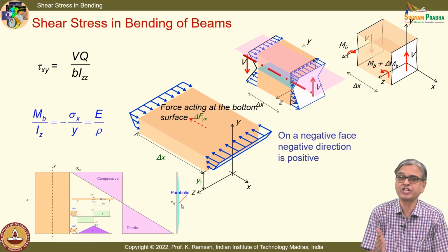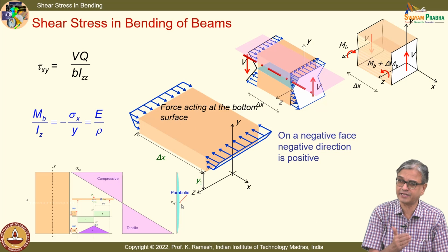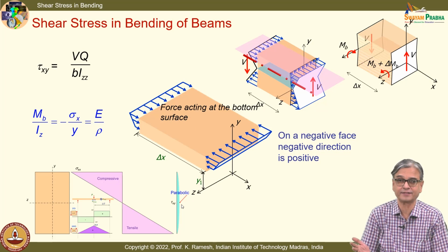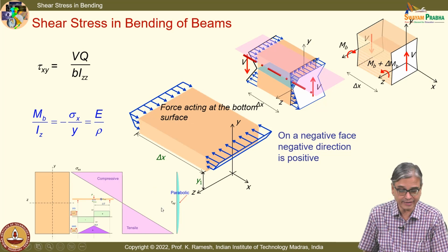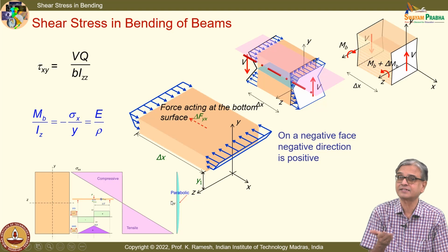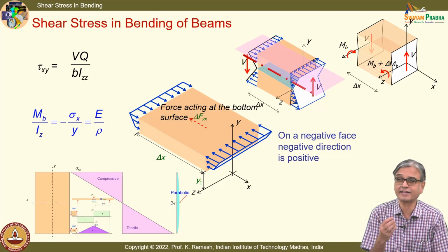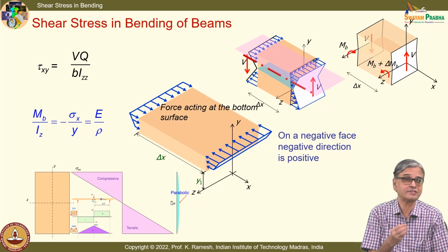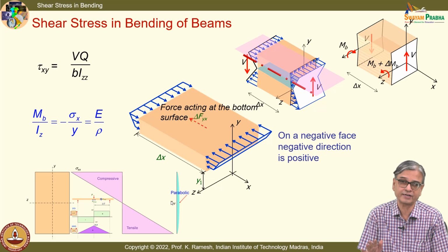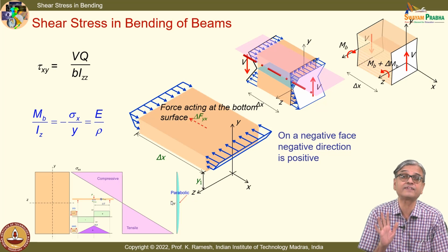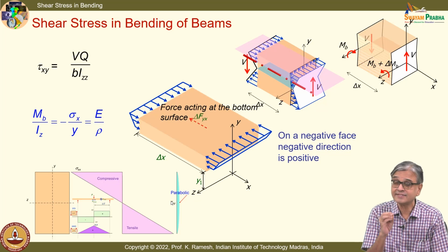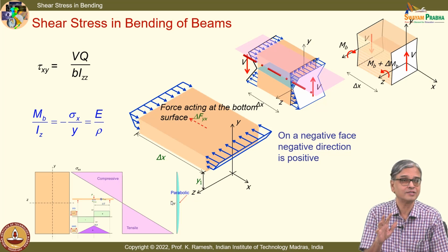Many books emphasize the variation: the bending stress varies linearly, whereas shear stress varies parabolically. That is also important knowledge. It is also pertinent that we realize that the shear stress magnitudes are very small, and for this case we have discussed, if my length is 10 times the h, then the shear stress will be 20 times smaller. So, you have to recognize, occasionally we will also say that shear stress effects are negligible, ignore it. There are instances where shear stress effects are very significant. You will have to be sensitive to that, where to use it, where to neglect it.